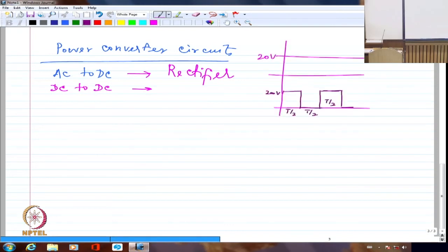Right? Looks kind of strange. Because how will the motor know you are giving voltage only for half the time? It will start rotating. That's what you might think. But this I will do at kilohertz or higher frequency, hundreds of kilohertz, whereas the motor has a huge time constant. Mechanical time constants are generally very large.